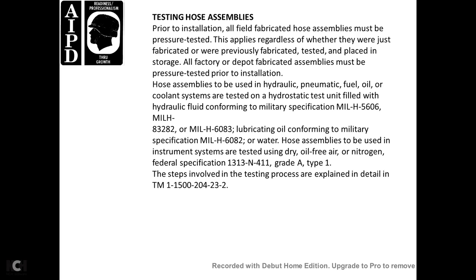filled with hydraulic fluid conforming with the military specification MIL-H-5606 and MIL-H-83282, MIL-H-6083, or lubricating oil conforming with the military specification MIL-L-6082. Hose assemblies to be used in the instrument system are tested using dry, oil-free air or nitrogen, federal specification BB-N-411, Grade A, Type 1. The steps involved in the testing process are explained in detail in Technical Manual